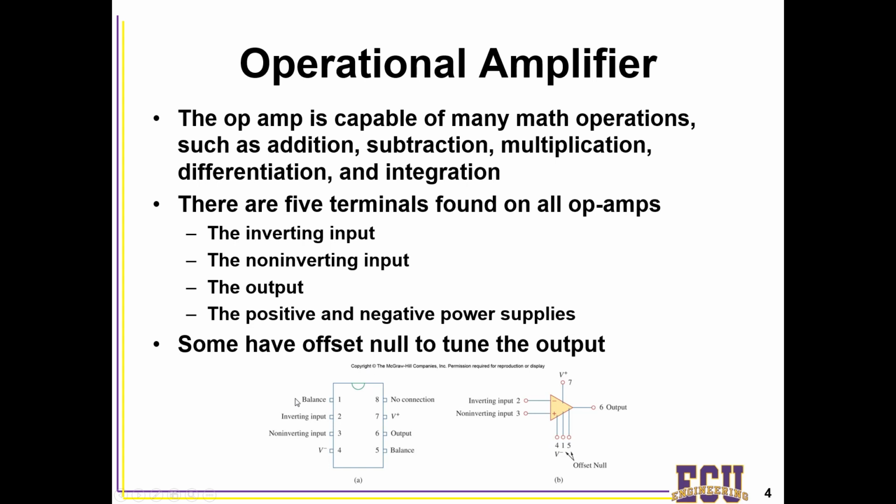This particular op-amp is in this dual inline package chip, which has 8 pins on it, and this will be similar to the one that you're going to be using in the lab. We'll actually be using 2 different op-amp chips in the lab in this class, and so one will be very similar to this one here, and it's important to note how you count pins on an op-amp or any dual inline package chip. Pin 1, if you notice where this little notch is, there will actually be a physical notch. Sometimes there's a dimple in the top of the package, and so if you orient that so it's up to the top, then at the top left is pin 1, and then it goes up through pin 4, and then you take this U-turn and you see pins 5 through 8.